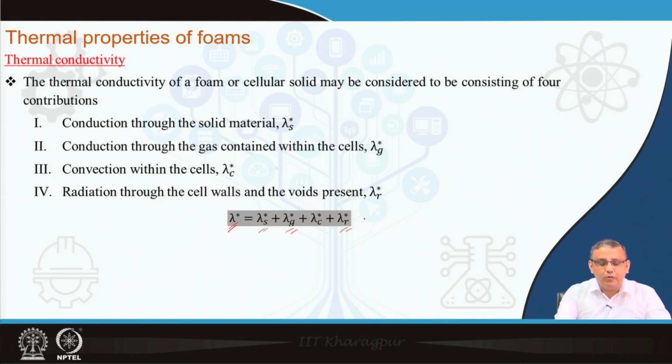Among them, the most important contribution comes from lambda S star. If it is an open cell foam made up of solid struts, or a closed cell foam made up of solid struts and faces, the solid of which the foam is made has the highest conductivity, because, as we know, gases have very low conductivity.